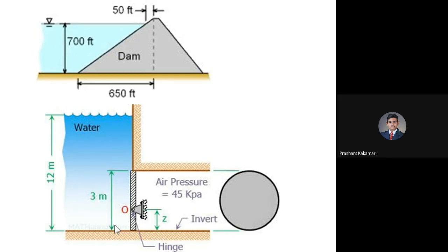The inverted triangle shape you can see is the water surface, which is open to the atmosphere. At the tip of the dam, where the intersection is, the force applied by water will be very small because it is at the surface. In rho g z, z will be 0. Exactly at the surface line, without any difference of head, the pressure may be negligible, zero.